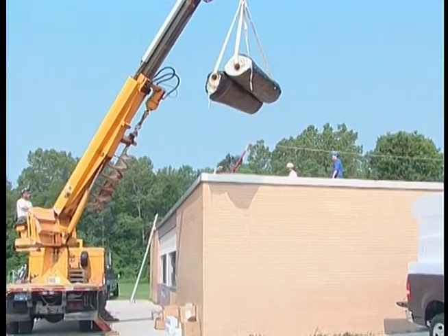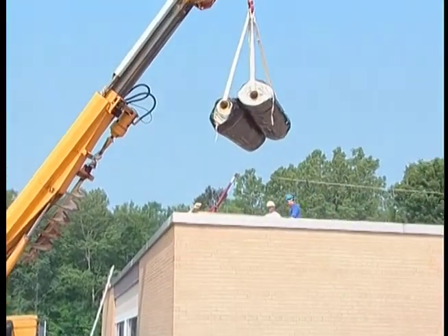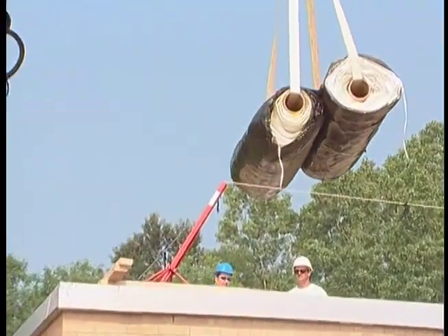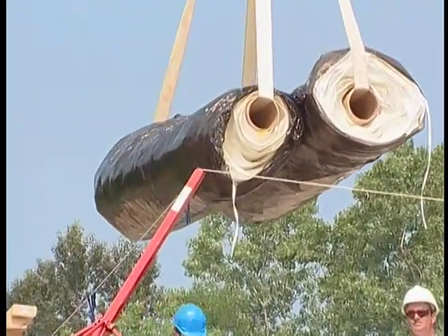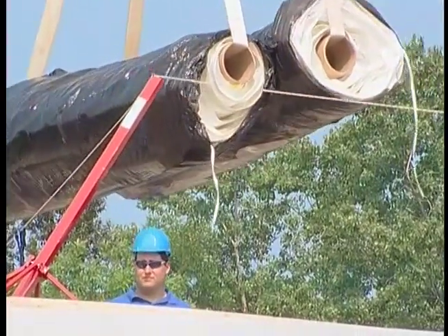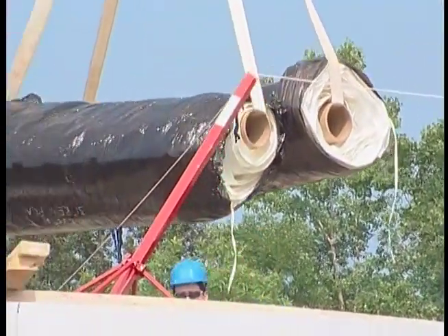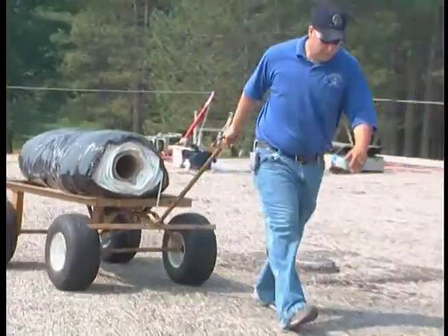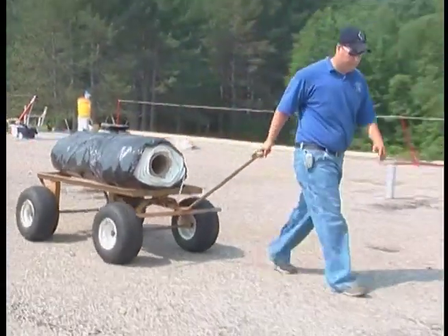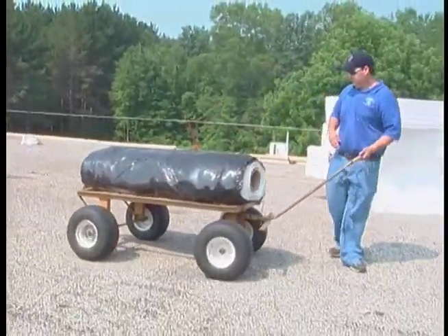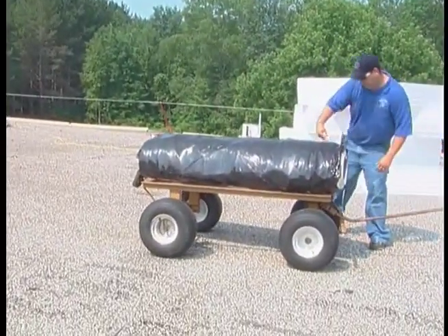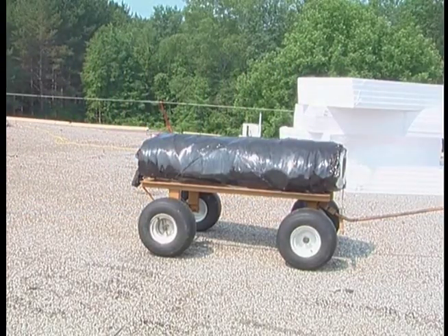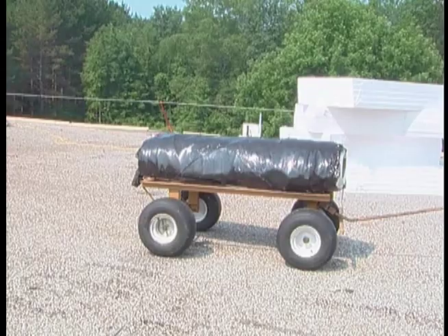During staging, you may need to use forklifts or other material handling equipment to stage your materials. When lifting rolls of roofing material to the rooftop, place them near their installation location to save labor and time later. Whatever methods, people, and machinery you use, you must place rolled, prefabricated sections of roof membrane on the roof near roof structural supports and in a manner that makes final installation convenient. Once you've placed materials on the roof, use a material handling cart to move them around.